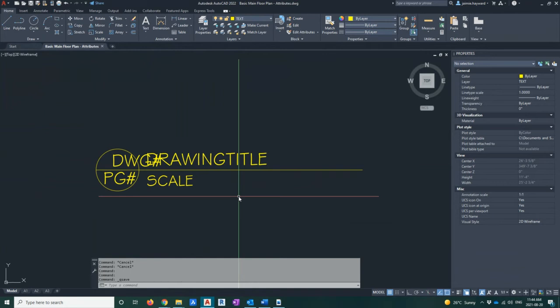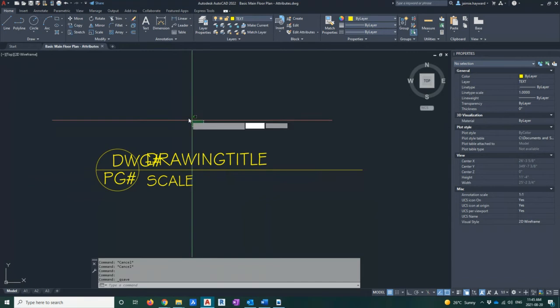You can see that this is totally a skeleton. This is what I mean by a skeleton. It's the bare bones. We've just created attributes. That's all we've done. It's quite useless the way it is right now. I mean, I could double click and fill this all in myself, but that's not the point of attributes. So now's the time we use block. Block is the key that we need to make the magic of attributes happen. So we are now going to move into using W block.